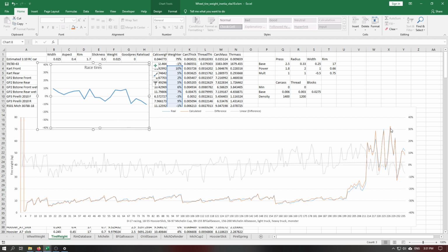And even if we do a truck tire, which we see here, it's still incredibly close with the weights. Light truck tires are a little overweight for some reason, but here you can see that one model, that's 1 day of work, and after that I will never have to think about the weight of the tire again. It also allows me to calculate the inertia of the tire, the resistance to rotation and acceleration and braking of the tire. Because that's now easy to do because we have a physical model. We have sidewalls with a certain dimension, and we know where that is. We have the thread, we know where that is, how heavy it is, and then you can calculate the inertia as well. So that's really important.